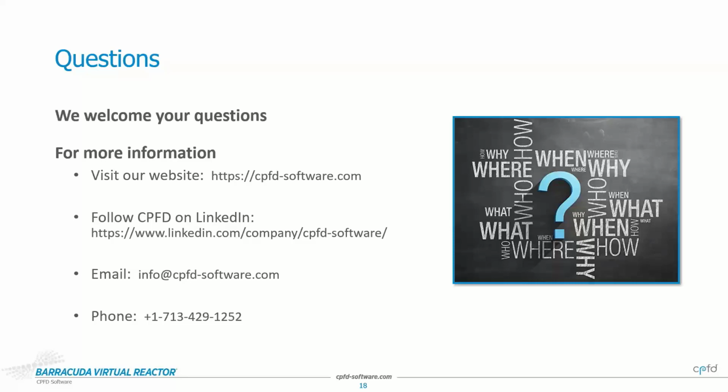Currently, the stress model in Barracuda is a global model, and basically you have to set it for everything. So it is not different for particles or droplets in the current release of Barracuda. It's a global setting that applies to everything. So be aware of that. If a different PS value, the pressure on the solids value, would be appropriate, then you'll have to adjust that, and it will affect all of the Lagrangian entities in the model.